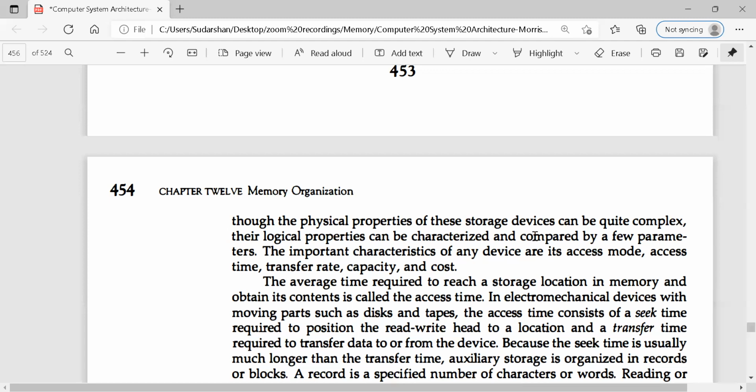This is in the case of a PROM. So technical details are not required. You can remember, in the case of PROM, writing operation is possible. You do writing with the help of a special device. By default, all the cells will have the value 1. To make it 0, you have to pass a very minute current, namely milliamperes or microamperes, to nullify the fuse or to remove the fuse. This is in the case of a PROM.